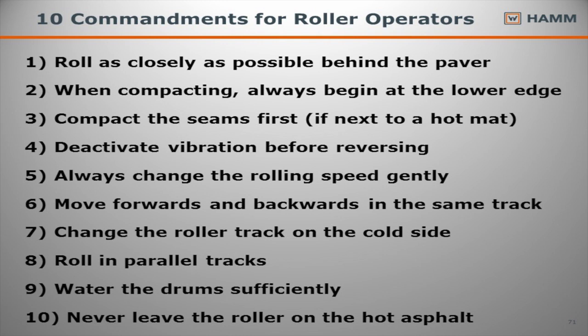Again, when we compact, I always like to compact from the bottom side up. Most all roads have some kind of a slope to them, and we have troubles with joints. So if you start at the joint and go out, you're pulling all the mix away from that joint. By doing that, you just have opened up the chance to have a bad joint. You start at the bottom and move your way to it, so you move all the mix towards the joint. You have a better chance of making a tighter joint.